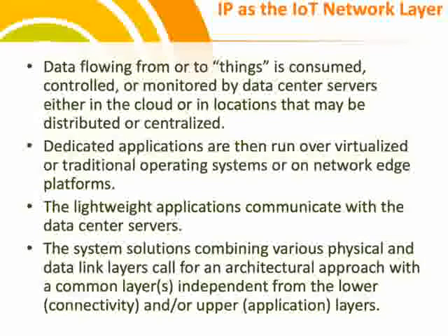So now what I do is, from 8 o'clock in the morning I prepare a dedicated application. Its job is to monitor the temperature throughout the day in that particular classroom. Now go back to the first point in this slide: the data is consumed, controlled or monitored. So the temperature data should be continuously monitored. Consider a situation where the temperature increases to more than 30 degrees Celsius, then I'll increase the speed of the fan. Increasing the speed of the fan is done by the dedicated application, and increasing it is nothing but controlling.